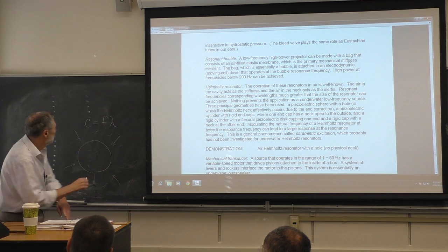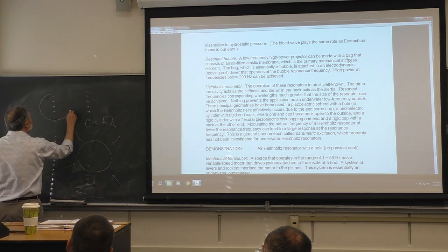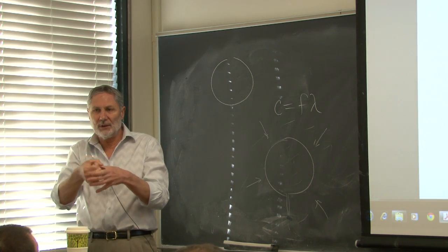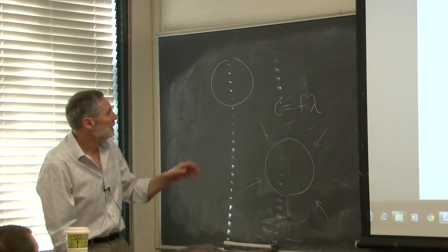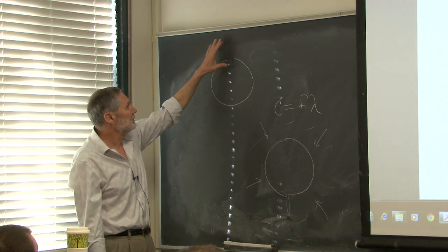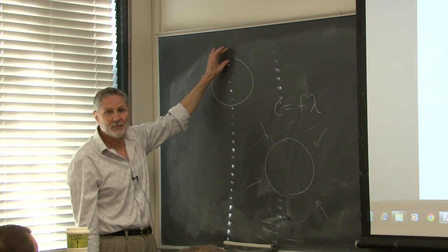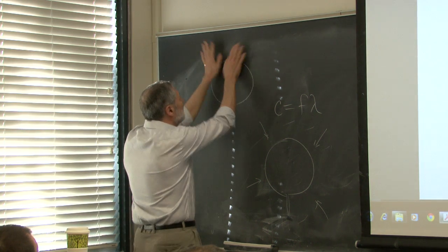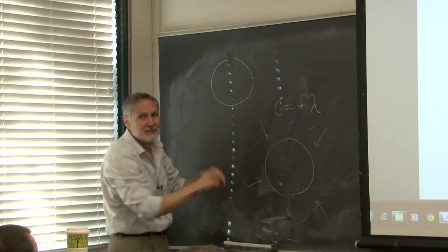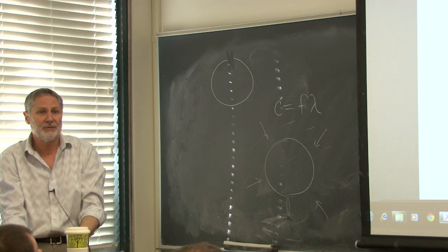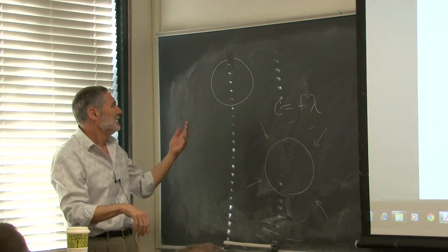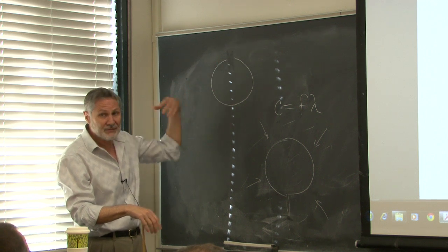Remember that? I demonstrated this in a previous course. We had this sphere, about this big, plastic and gray, with a 1-inch diameter hole, and I blew across the top. There's very little thickness here, but there is an effect due to the end correction. The pressure doesn't equalize here. You effectively have a neck just due to the flow there, and we actually calculated that in the previous course. So this is what we call a neckless Helmholtz resonator. It's physically neckless, but there is effectively a neck.